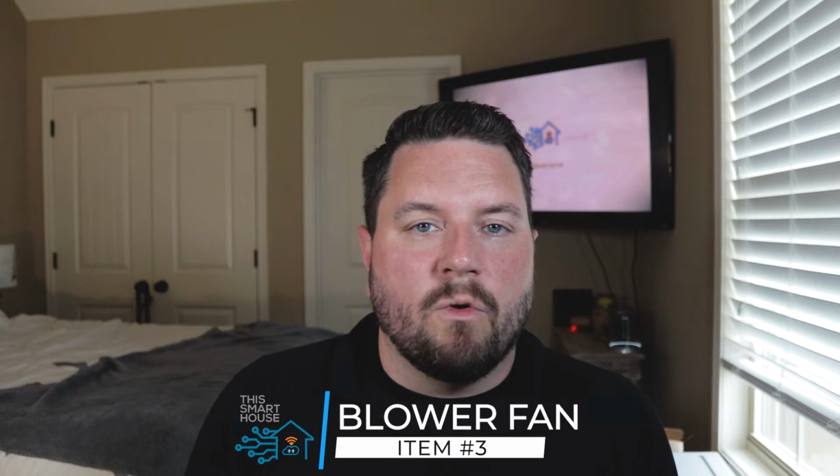All right, so the next most common problem is that your HVAC fan has failed. So this would be the blower fan that's actually in the bottom of your furnace and air conditioning combo unit. This is what pushes the air out when the system runs. When you tell the air conditioner to run, you don't hear anything on the inside. You don't hear that characteristic humming of the fan, and you put your hand over the vent and there's no air coming out. So that would indicate that maybe there's a problem with your HVAC fan.